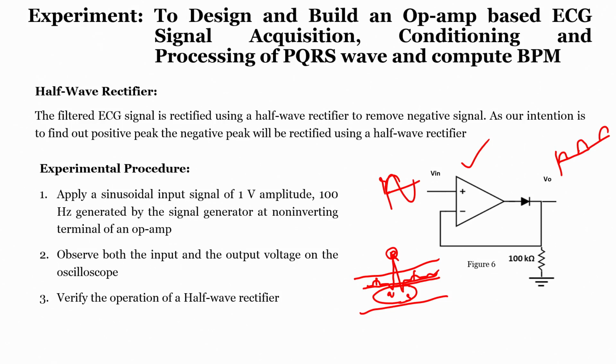That is the reason, as we already know that the QRS peak is very long, having a very high amplitude compared to other peaks. If we can detect this particular peak, our problem is solved. So, in order to detect that, we are using a capacitor which stores the complete highest voltage, but how do we create a threshold? And if I can create a threshold, and compare the output signal with the input signal, then when we do the comparison, whichever is the highest, I can decide it.